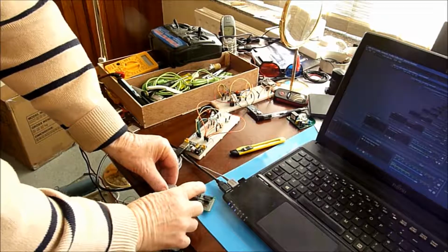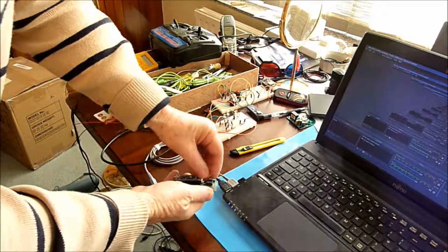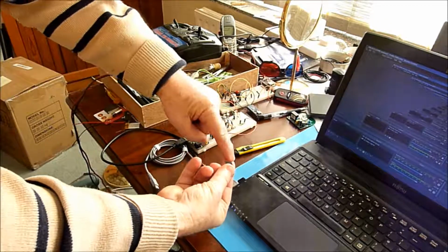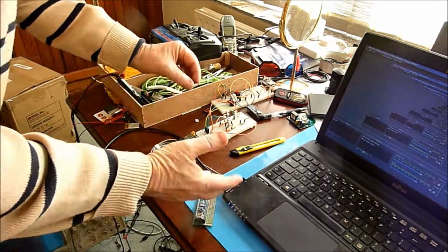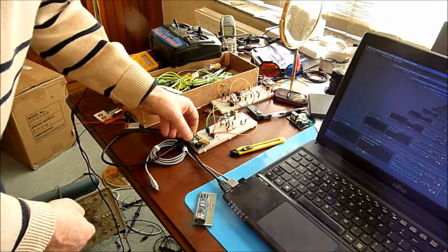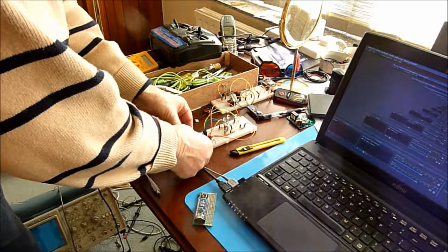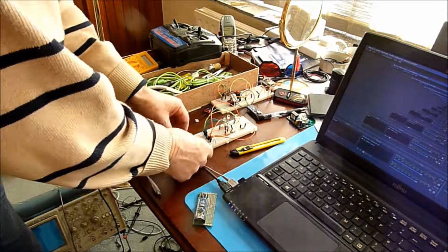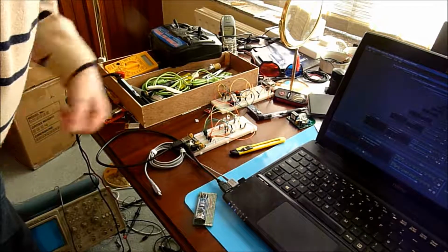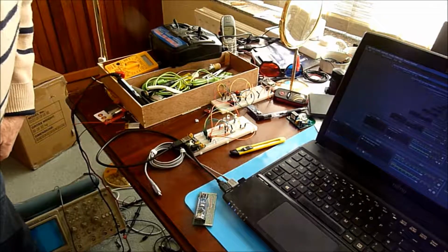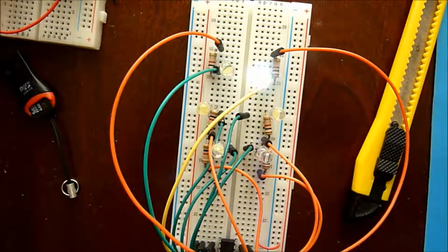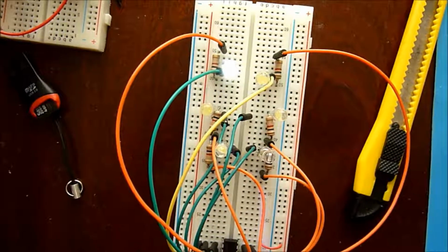So now we unplug that, because you never like to unplug chips with power on. Take the chip out. Always make sure where pin 1 is, because, well, I've done it before. If you plug it in backwards, they die. Plug it into the breadboard and let's try it. And there's LEDs running around in a ring. Taking about a half a second per LED.